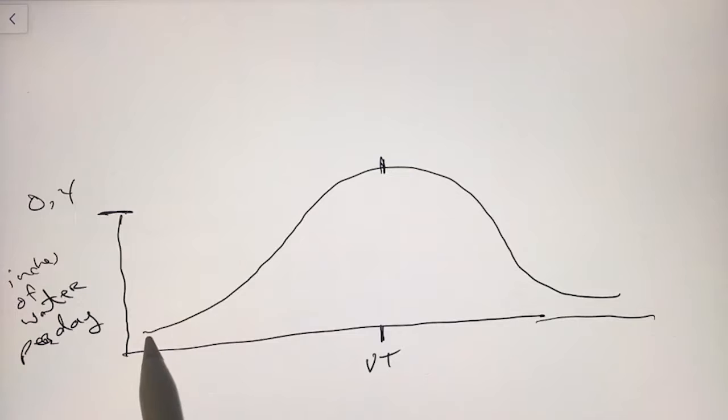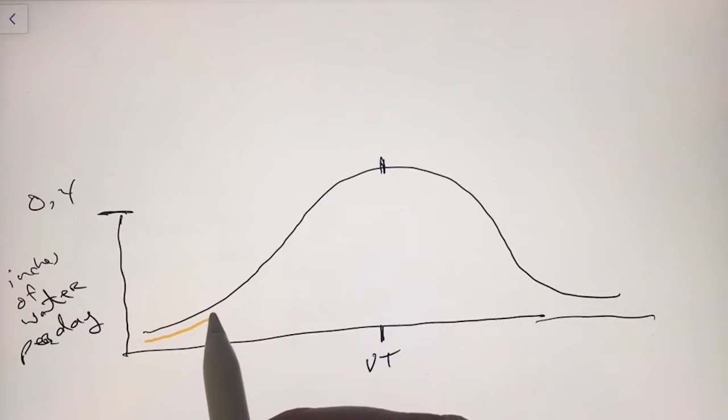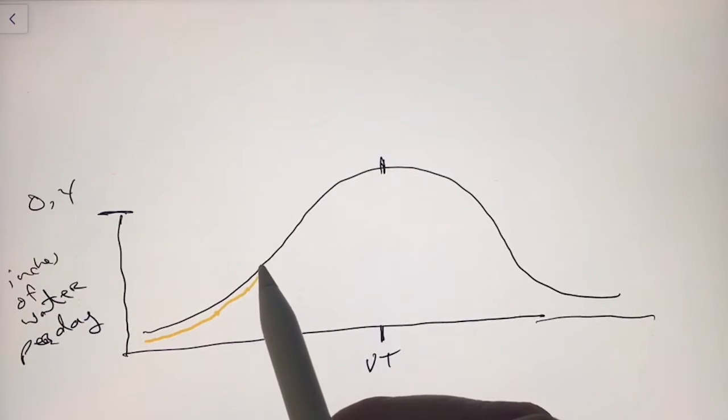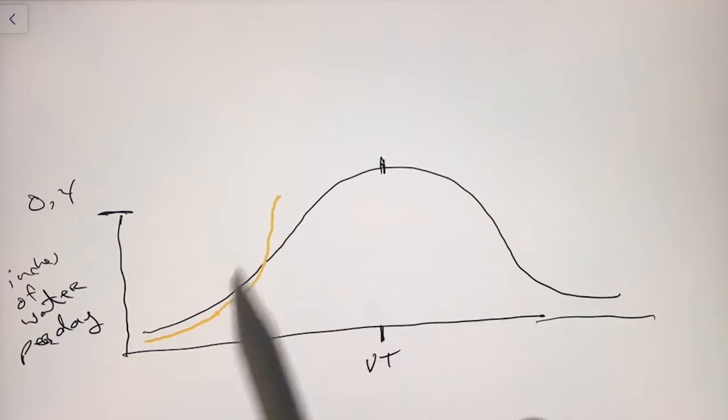So here we say the yellow line is representing what's happening in a particular year. So we've got the crop water use being tracked close to what's occurring on average. And then we enter into a time frame where we see higher than normal water amount being used by that plant because we have warmer temperatures with low relative humidity. And let's say it's a 95-degree day with a lot of sunlight and a lot of wind. And this occurs for a week.